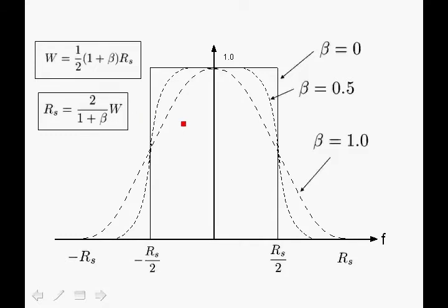This is very interesting. This shows that by controlling the roll-off factor, thereby controlling the amount of excess bandwidth, as you can see over here, we can actually improve the throughput through the channel. So the maximum throughput through the channel is achieved with beta equals 0. And if we use beta equals 1, then we get half the maximum throughput. So there's a basic trade-off between having a filter which is broader in the frequency domain and therefore time limited, which is what we need, and at the same time the throughput of the system.